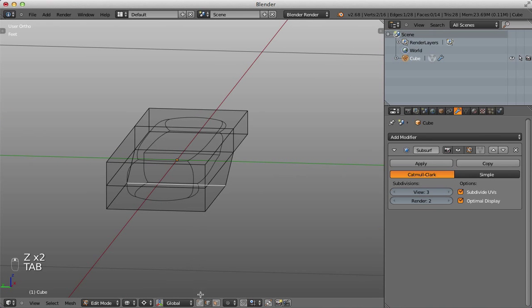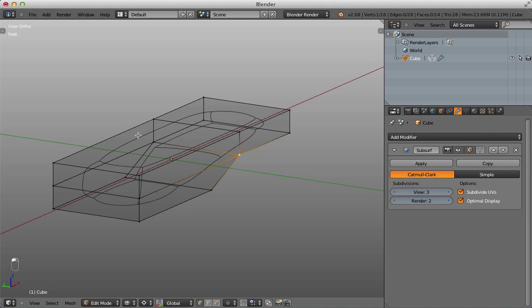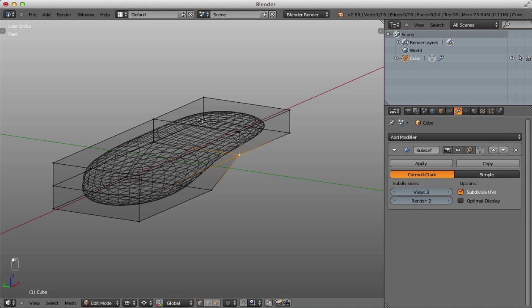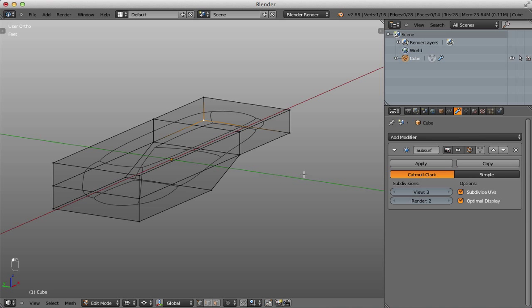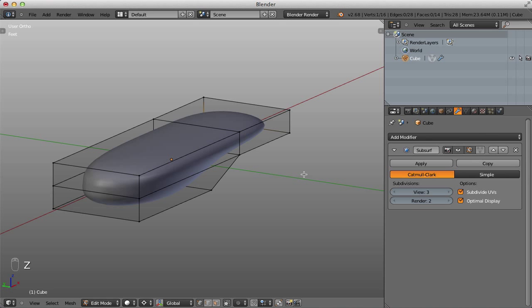Specifically, when you go into edit mode, this helps really a lot when you want to select points, because otherwise the wireframe mode or the wireframe actually starts hiding your points or makes it harder to click them. Okay, now it's time to add some loop cuts, so we can start giving this blob a more refined look.